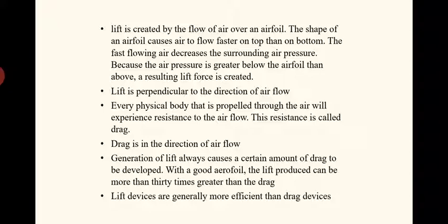Lift is created by the flow of air over an aerofoil. The shape of an aerofoil causes air to flow faster on the top than on the bottom. See, because of that shape, the air over the aerofoil will have higher velocity than the air at the bottom portion. The fast flowing air decreases the surrounding air pressure. See, only at the expense of the pressure can we increase the velocity. So that's why in the upper region we will have low pressure. Because the air pressure is greater below the aerofoil than above, the resulting force is created. So if the pressure difference is there, of course an upward force is created. That means the blade will be lifted upward. That's why it is named lift. Okay, and the important thing is lift is always perpendicular to the direction of the airflow.